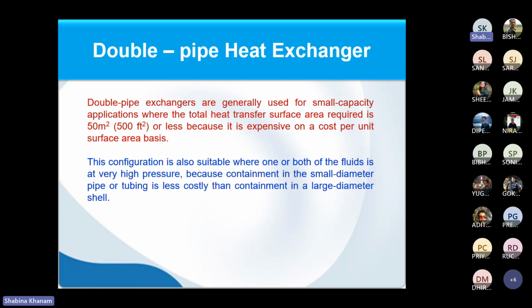If you go back to the previous course, CED1, what we considered was the thickness for a pressure vessel, right? The expression we discussed was P D naught by 2 Fj plus P. Remember?